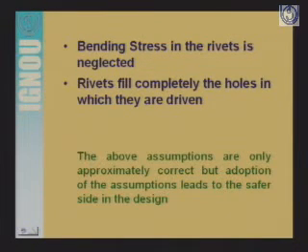There may be a little bit of gap because of the non-uniformity of the hole or the particular shape of the rivet. In that case there may be a little bit of gap, but here for design purpose we are assuming that rivets fill completely the holes in which they are driven.